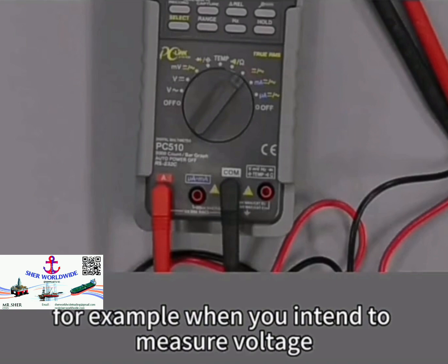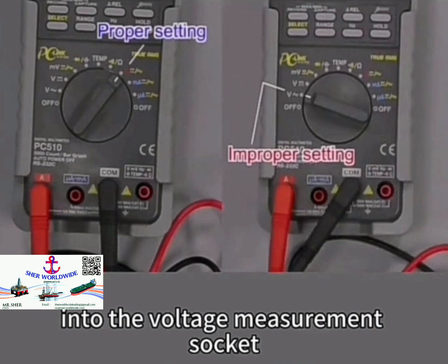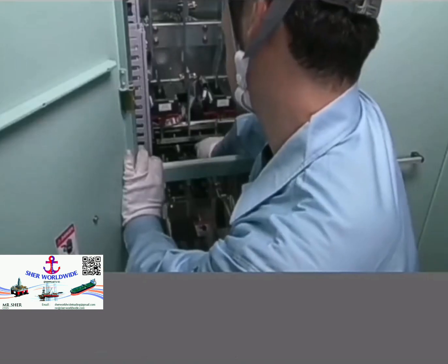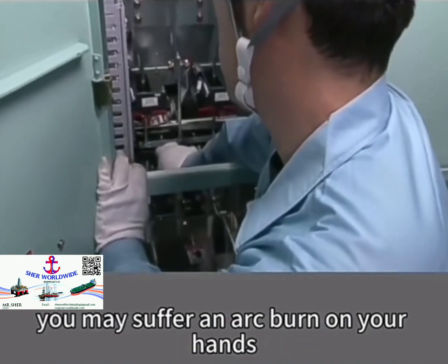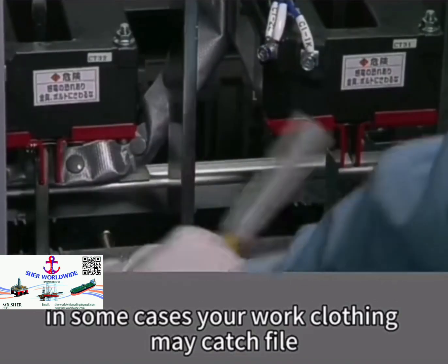For example, when you intend to measure voltage, check whether the probe is inserted into the voltage measurement socket, and whether the measurement range setting is correct. If a ratchet touches a terminal while you're working, you may suffer an arc burn on your hands. In some cases, your work clothing may catch fire.